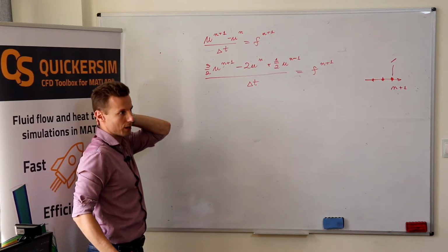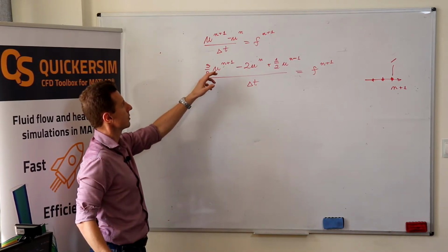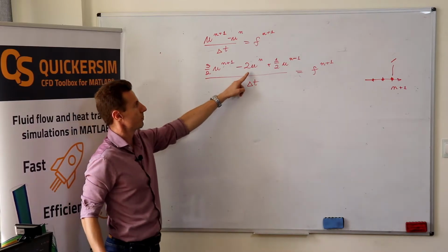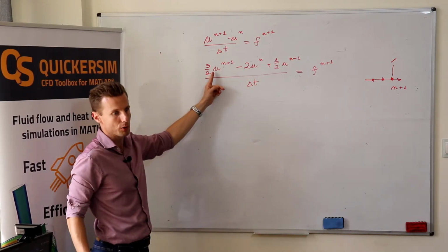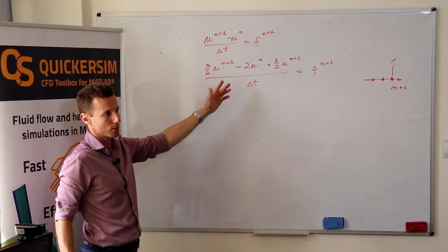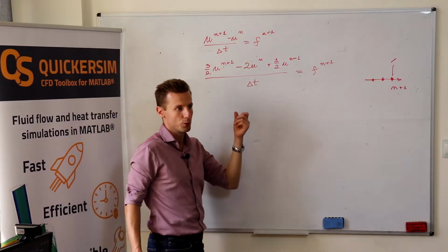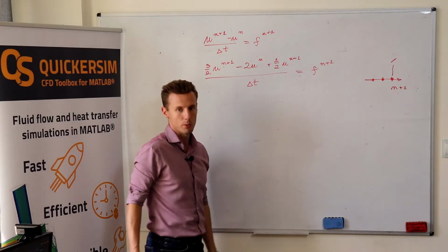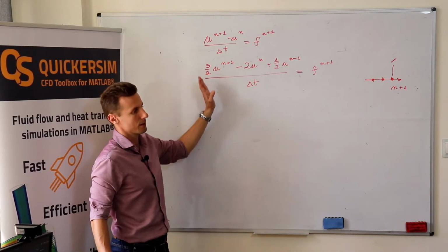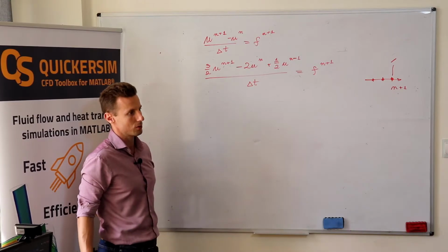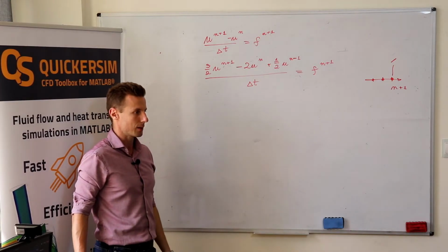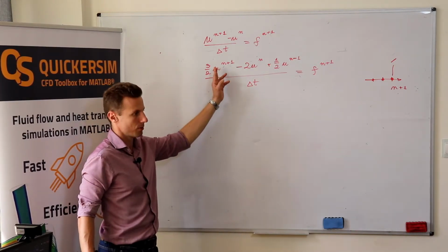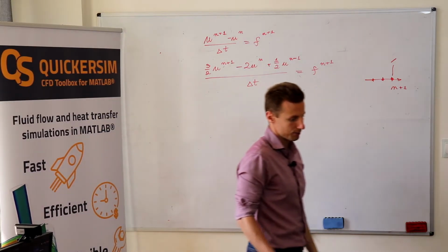What it changes is that it requires you not only to remember the previous time step and calculate the new time step, but to store two historical solutions during the time stepping process, and you only make a minor modification to your left-hand side matrix to discretize the time derivative.